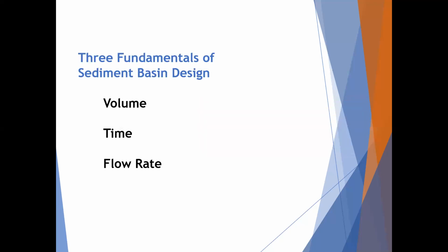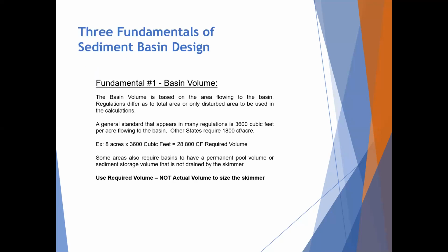So we'll get into the 3 fundamentals of sediment basin design, and those are really simple. It's volume, time, and flow rate. So the first fundamental is basin volume. The basin volume is based on the area flowing to the basin.